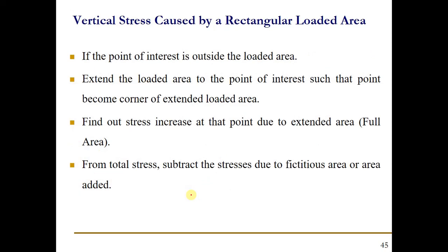Now we will use another figure. I will show you how we can find out the delta sigma at various different points. For example, at the center of the rectangle, at the side of the rectangle, or even outside of the rectangle as well. So if the point of interest is outside the loaded area, we need to extend the loaded area to the point of interest such that the point becomes the corner of the extended loaded area, as we have done here.